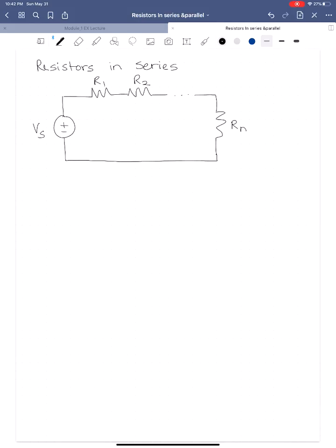All right, because this is a series circuit, there's one current flowing through each one of these elements, okay? I'm going to label that current right here, and I'm going to call it I sub S. I sub S is the current that flows through each element. It's got to flow from minus to plus through the source, so then it will flow through the resistors by going in a clockwise fashion here. There's only one source in the circuit. It has to be delivering power, so the current's got to flow from minus to plus.